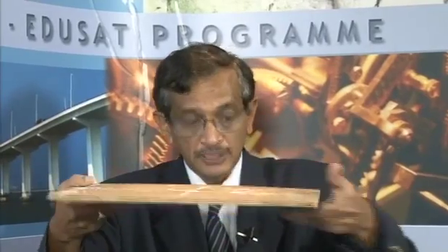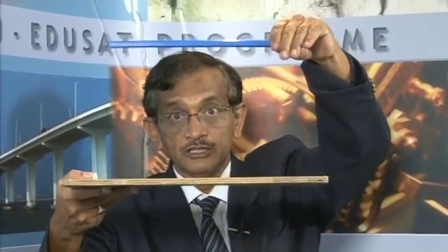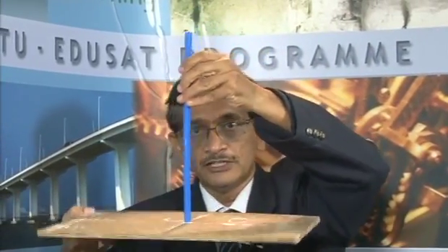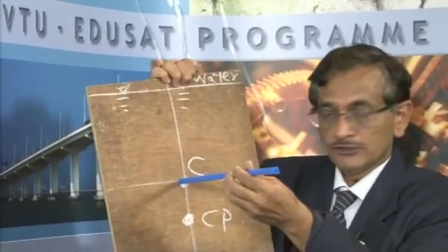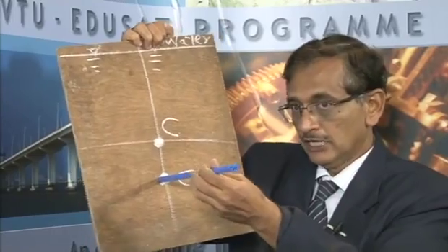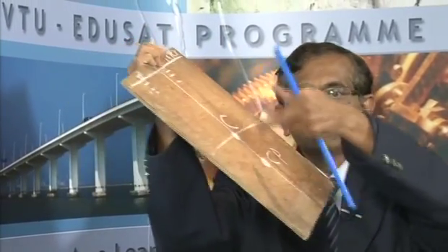So I stop with my today's discussion. I know that it is a bit heavy today, but mind it well, today we have covered what is the force acting on this particular submerged plate under water, which is submerged up to this level. So everywhere pressure is the same, center and center of pressure will be the same, this we will be acting like this exactly. Then we have understood how it is going to be working on the inclined plate. Center of pressure will be here and centroid will be here. So force will be acting here, right, and when it is inclined, somewhere it will lie between C and Cp.